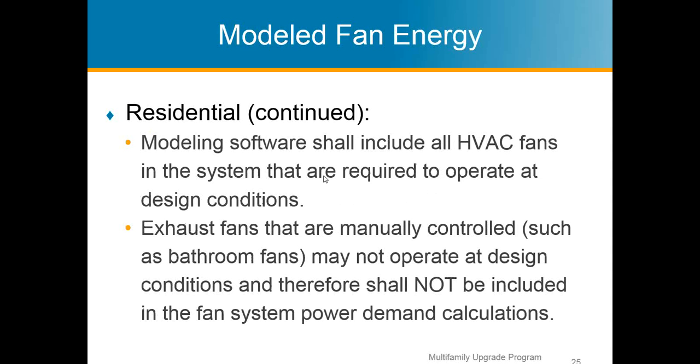This is just straight from EnergyPro. Modeling software shall include all HVAC fans in the systems that are required to operate at design conditions. Exhaust fans that are manually controlled, such as bathroom fans, may not operate at design conditions and therefore shall not be included in the fan system power demand calcs. Now, you can put them in as side calcs. You can figure out what that is on the side, but it's going to be hard to quantify it.